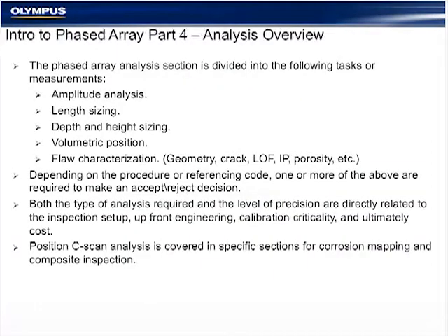That was done using a weld rover automated scanner that doesn't require a laptop. It's just simply a handheld paddle that goes forward and backward at a fixed position. It had a laser that was walking on the weld line that allowed me to guide it while I was looking at the OmniScan periodically.